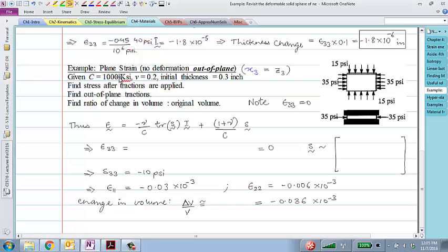It is an assumption in beam theory. That's true. In the axial direction, we actually assume that the plane itself is rigid, but the plane adjacent to it, we do allow deformations between those two planes, right? So beam theory, in that sense, wouldn't fit this particular state of strain.